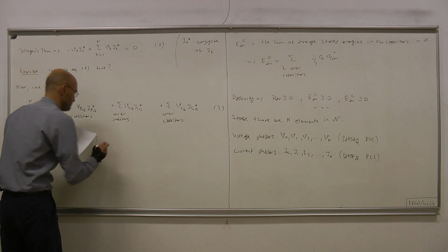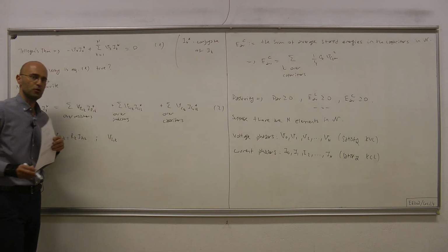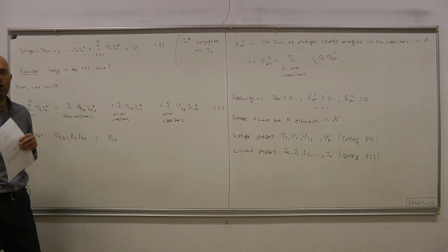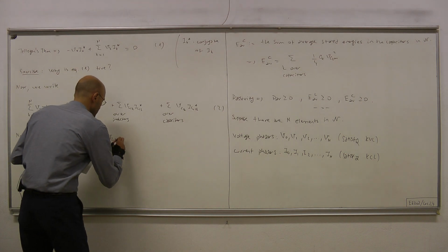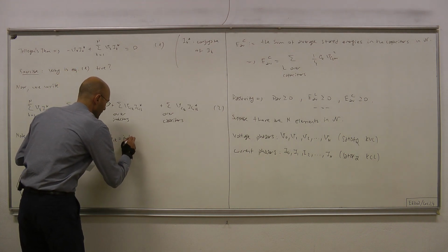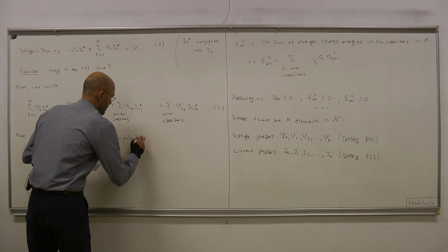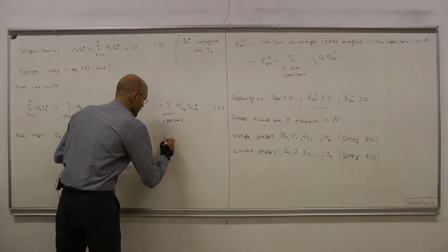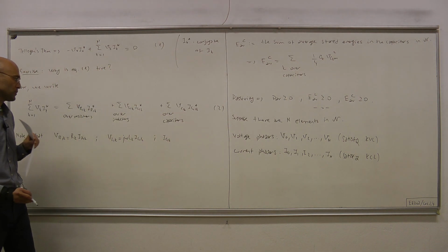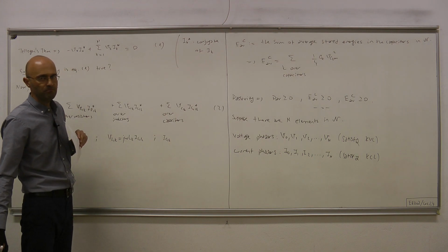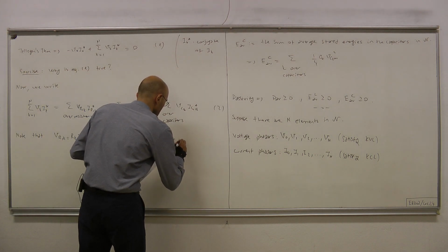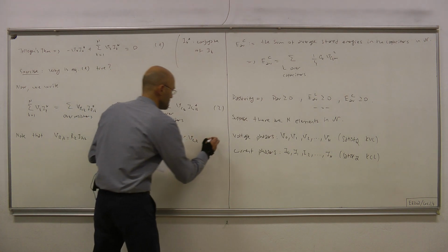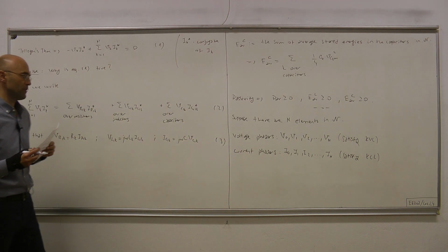As for the inductors, voltage equals the impedance times the current, and the impedance for an inductor is j omega L. So VLk equals j omega Lk times ILk. And as for the capacitor, we write the dual identity: current equals the admittance times the voltage, j omega C times VCk. And this is our third set of equations.